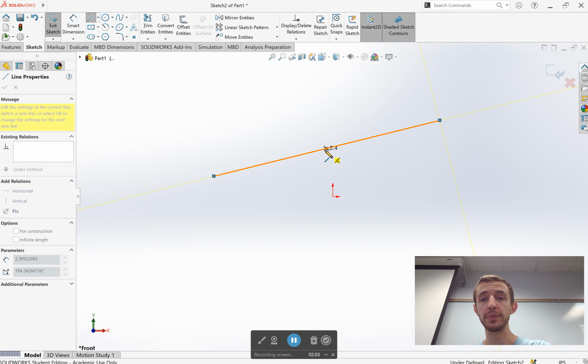And also you can see that the midpoint of my line is shown. If I wanted to, I could click to that. Other things you'll see is that I can see the point where I'm going to be horizontal with the original point of my line or with the top of my line. Either one of those relations can be added in there. I can also do it where I am vertical to that point. So I'm directly underneath it, right there, or directly over it right here. Lots of different things I can do here. At this point, I am both horizontal to one point and vertical to the other. So there's a lot of things here to help you out when you're drawing your lines.